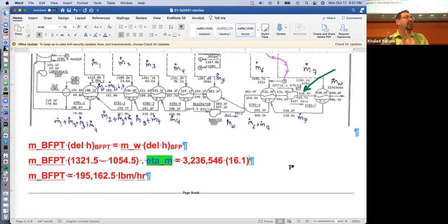You would say that you don't expect a turbine sitting next to a pump to send the work with 100% transfer between them. What do you expect in between? Are there any losses between a turbine and a pump sitting on the same shaft? There is bearing, right? Bearing losses, mechanical losses. Maybe they don't run at the same speed. Maybe there is a gearbox between them. So some kind of eta mechanical. Even if you just assume one, but you write some kind of eta mechanical, that shows really great understanding of what the physical system actually looks like, right? But so far, I didn't see this happening.